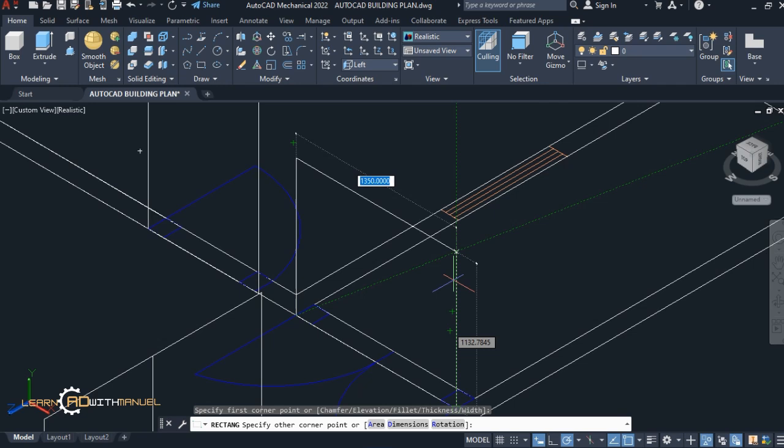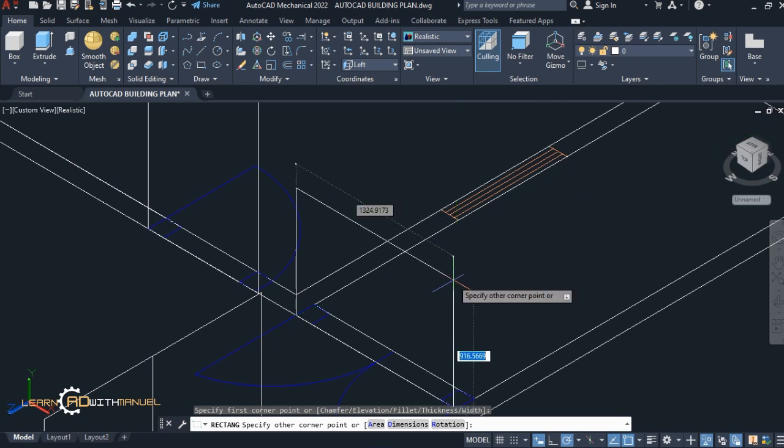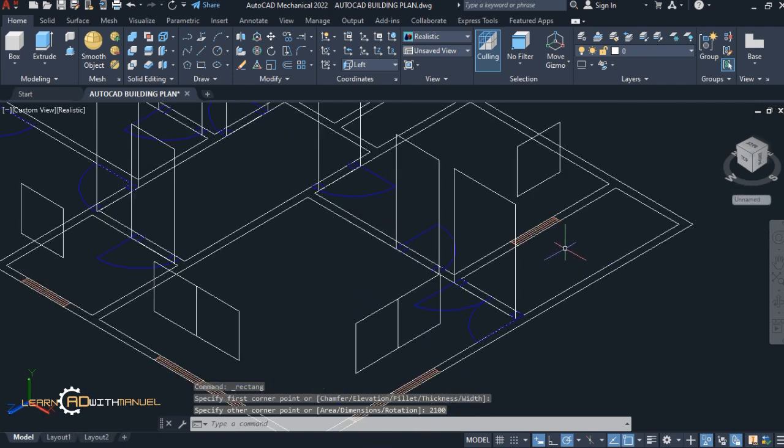That is the width of the living room door, and obviously the living room door is going to be bigger than the rest of the doors in the apartment. After doing that, we hit the tab key because that is going to be the default number for the width of the door. Then we type in 2100 as the height, as you can see.